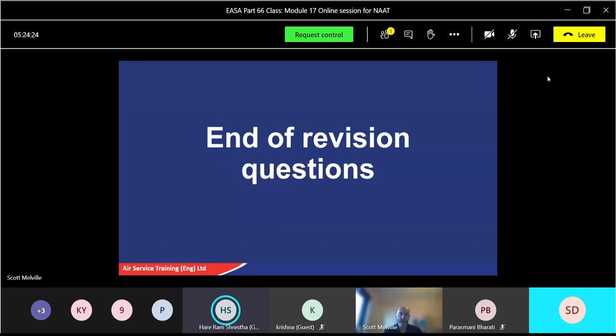If you're finishing a blend on a typical camber face, after removing visible damage, what must you also remove extra? You see the damage, you go down to the damage, and then how much more do you remove after the damage? A very small amount. 30 times, that's the depth over distance, but how about the depth?